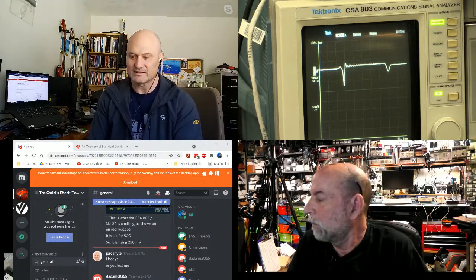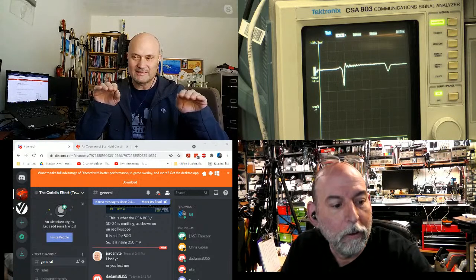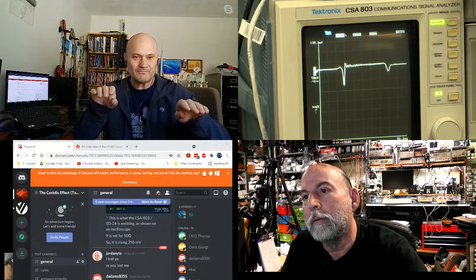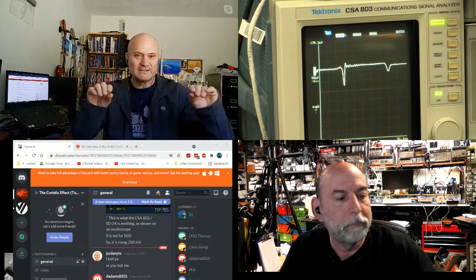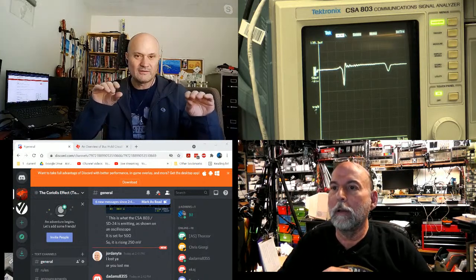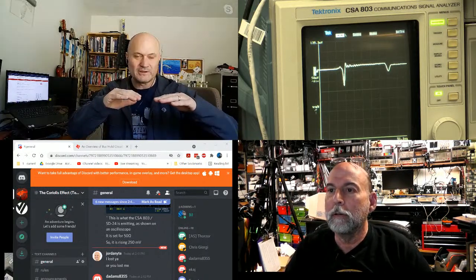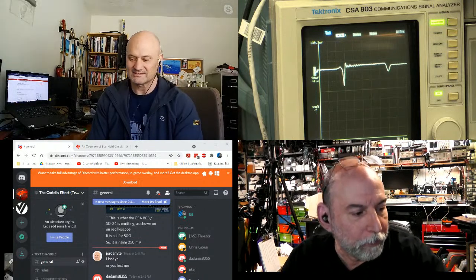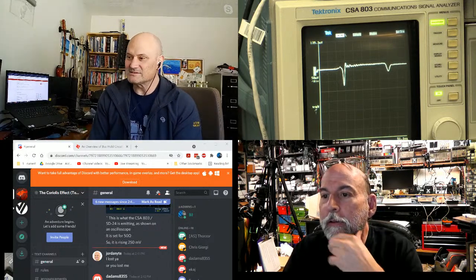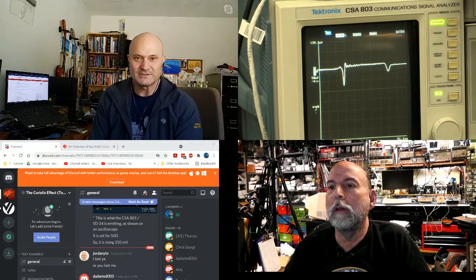So that's like a rigid flex. It's a polyimide substrate. It may be 2 layers of copper, or even 4, all done with polyimide instead of regular FR4, all attached by glue adhesive to aluminium, and the adhesive and even polyimide is lousy at conducting heat. So you get some heat through to the metal, but even then it's better than nothing. But I still feel like the industry hasn't really come up with an ideal solution yet.